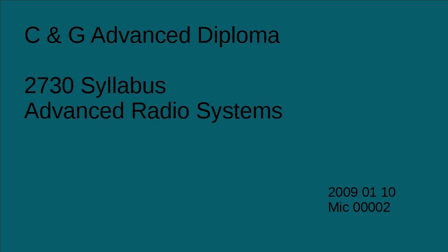Right. We now realize that the d upon lambda ratio is a very important thing. So if the lambda is small, even with a small diameter, I can get very high gain. Gain is proportional to (d over lambda) square.